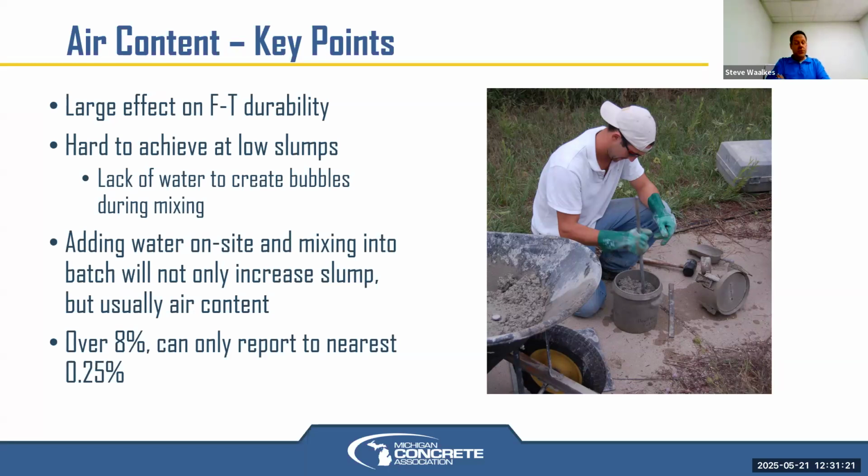There are air detrainers that do exist. MDOT does not allow them, but on commercial and other jobs we have seen it, or other jobs that use other admixtures that tend to foam up that are not air entraining admixtures, but they have a surfactant in them and tend to foam up somewhat and add air to the concrete, even though it's not air that we want.